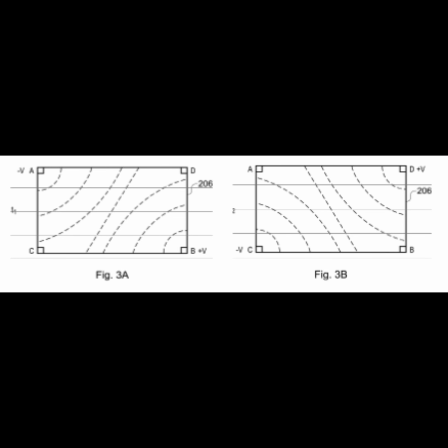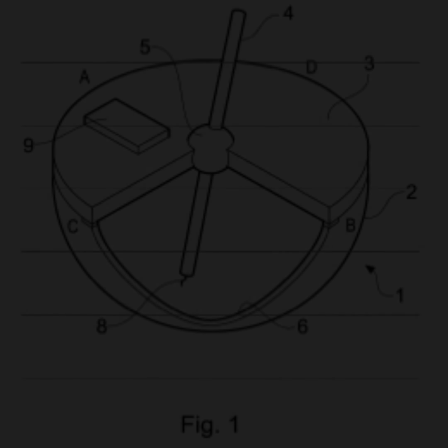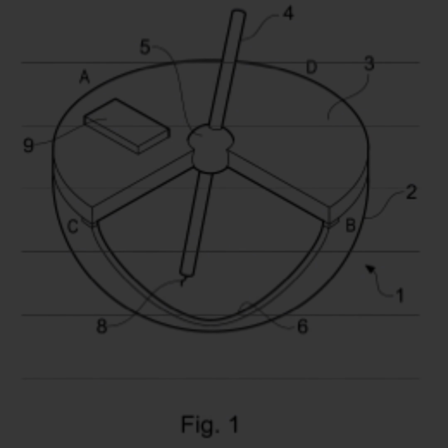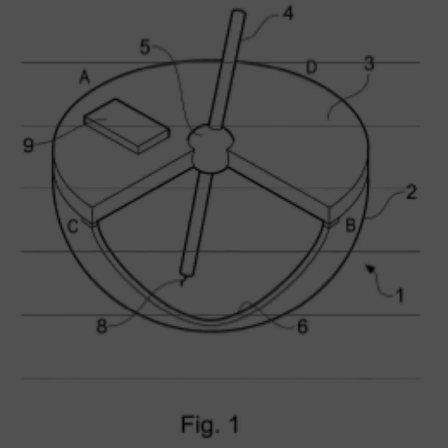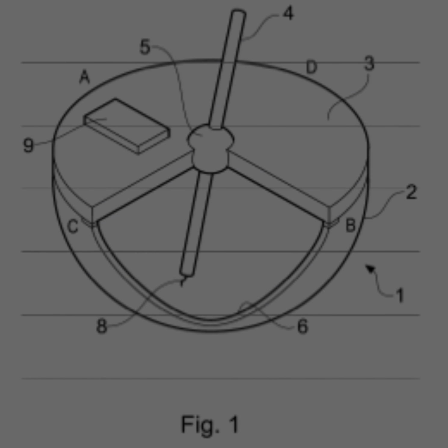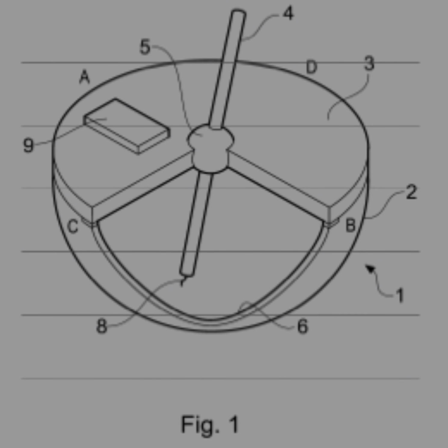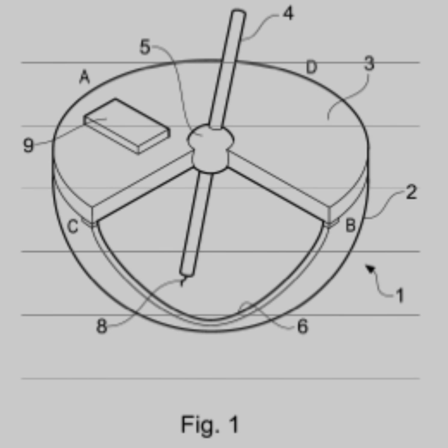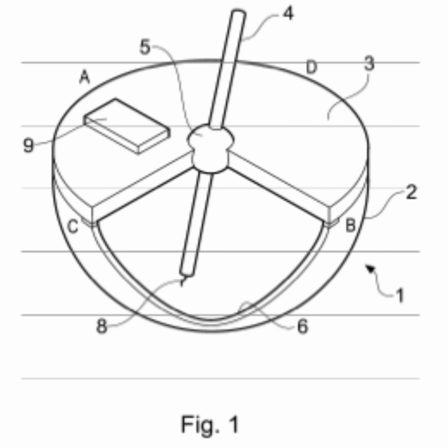When the conductive element 118 is in contact with the separating region 120, no voltage is picked off. As soon as the control unit 119 senses this condition, it continues to generate the output signal derived from the voltage previously picked off by the conductive element 118. In this way, the control unit 119 continuously generates an output signal that approximately represents the position of the actuator 114.